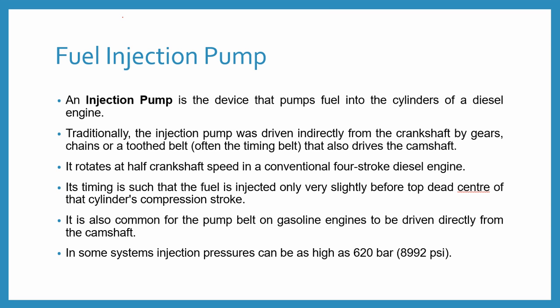It rotates at half crankshaft speed in a conventional 4-stroke diesel engine. Then its timing is such that the fuel is injected only very slightly before the TDC of the cylinder's compression stroke.